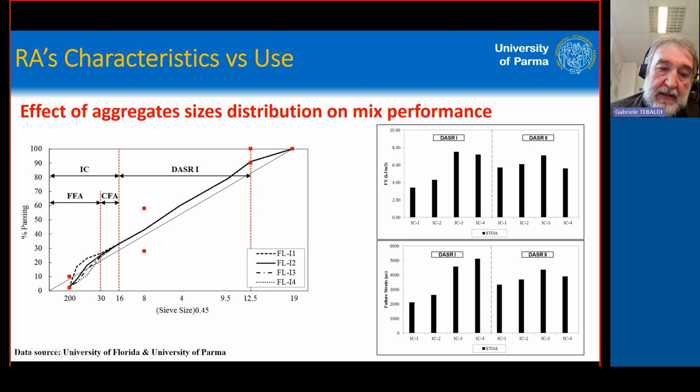Here, the project goal was to understand the behavior of the mixture, changing the original size distribution in three ways, but all the size distributions analyzed were inside of the standard requirement. If we look at the right side of the slide, you can see how the different mixtures behave in terms of fracture energy and failure strain.